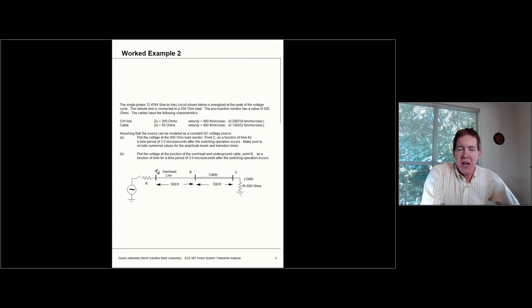So I would have this waveform traveling down that would correspond to possibly 7.2 kV RMS, multiplied by square root of 2 to get the line to neutral peak value. But that waveform traveling down the line might cause too much stress on the cable or on the load.